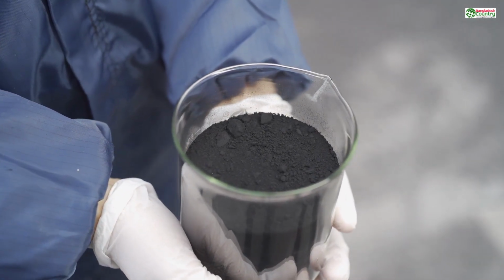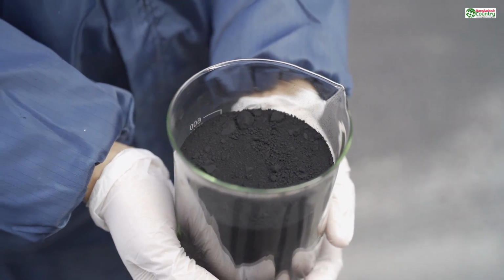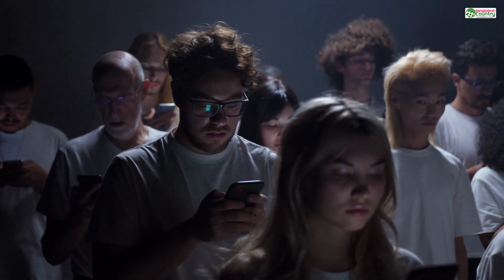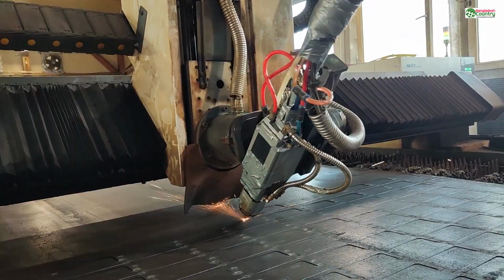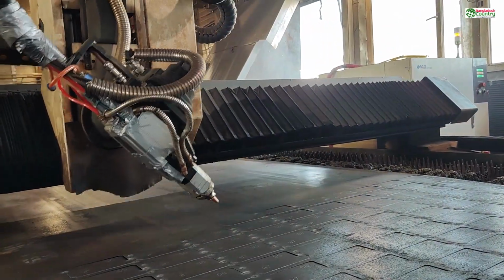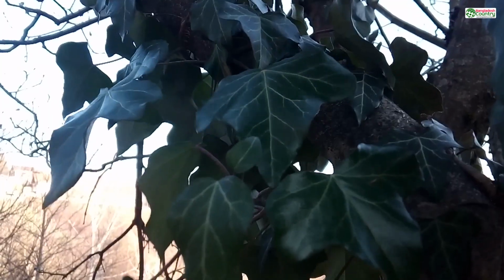And for the industrial powder-based systems used by most online services, like SLS, where a laser fuses together grains of nylon powder, a thin wall is like the edge of a sandcastle. The laser might not be able to fuse enough powder together to create a solid structure, leaving you with a fragile, crumbly edge that can disintegrate during the depowdering process.